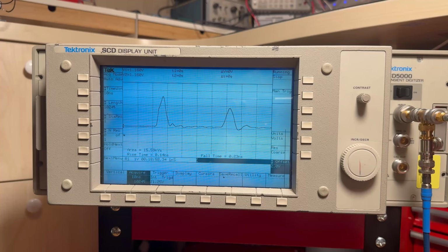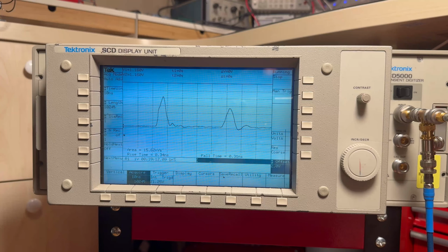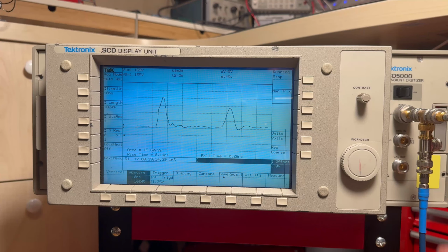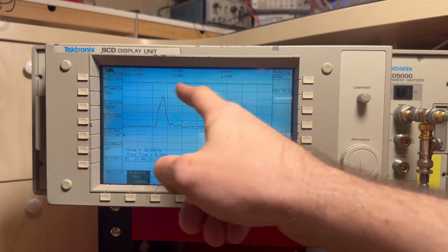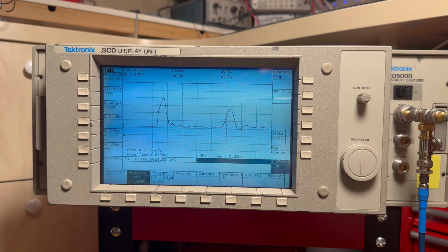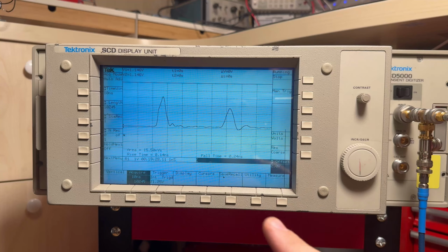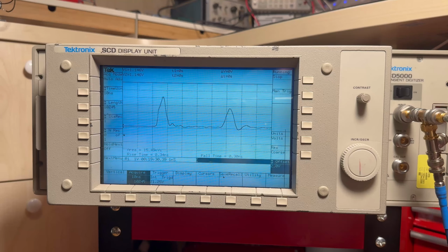So, yeah, it works as a TDR. The pulse is a bit shorter, and that's because of attenuation, but it's also because of some impedance mismatching and, you know, the adapters and stuff like that. Theoretically, this pulse would have been almost the same height as the incident pulse, because there's no lost energy when the pulse hits the open end of the cable.